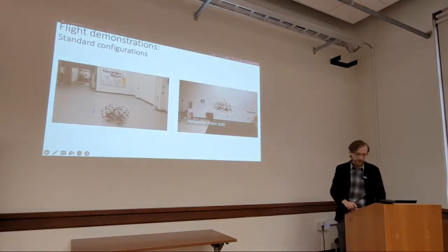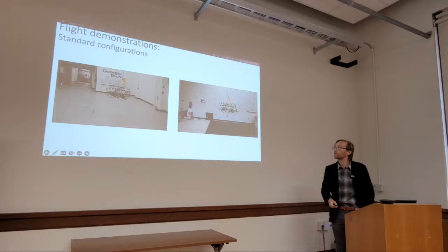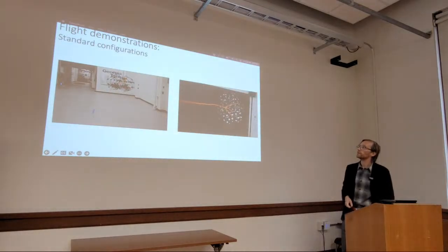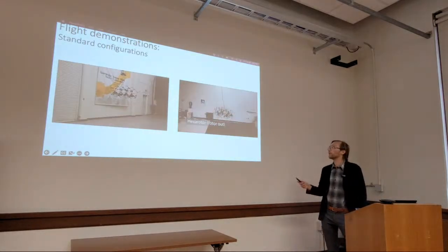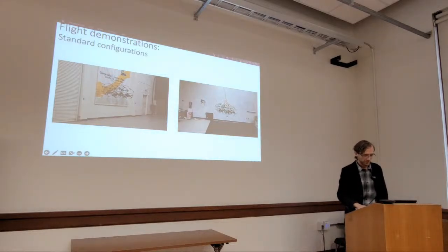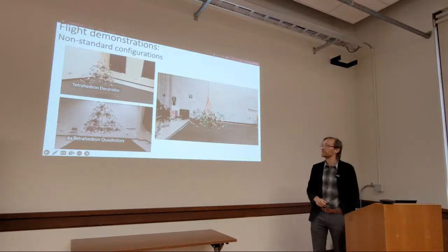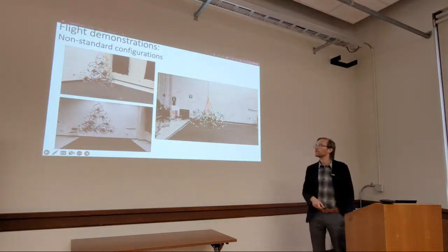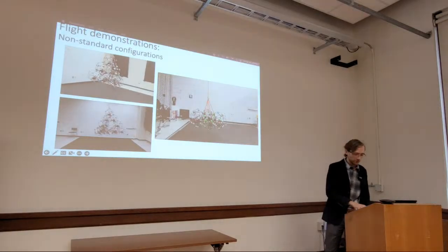We had a couple of flights that were performed. Here we see the quadcopter version. Here that was just a hexacopter flight with one of the rotors disabled. So it's actually a non-standard hexarotor configuration. And we also flew, a little less successfully, the non-conventional configurations. They're actually much harder to control.